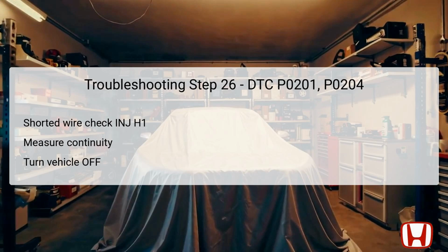As with previous steps, ensure the vehicle is off while testing for continuity. By measuring between the designated test points, you can verify the health of the wire. Should continuity exist, it suggests proper wiring is in place for injector operation. Absence of continuity necessitates immediate action to rectify the fault, ensuring the injector circuit can operate flawlessly. This step completes the troubleshooting process, reinforcing the critical need for electrical integrity within the system.